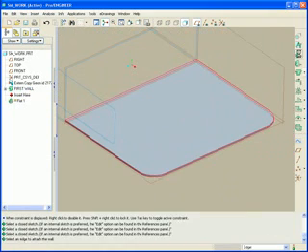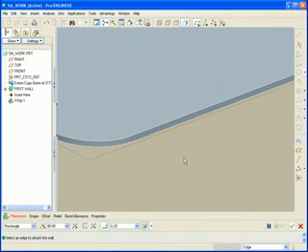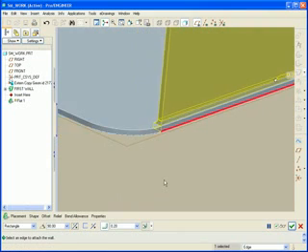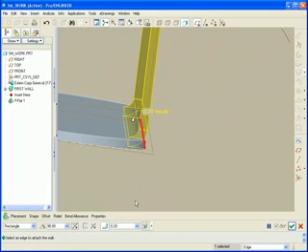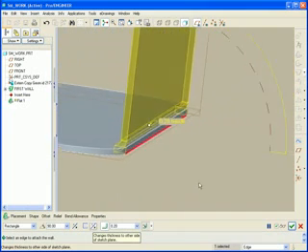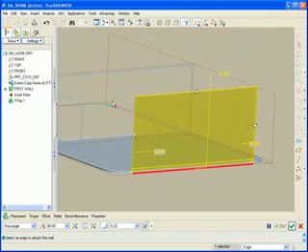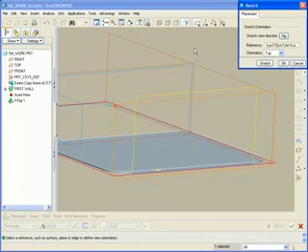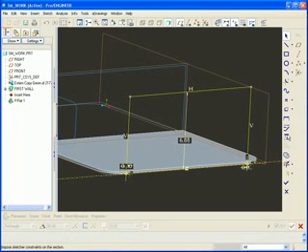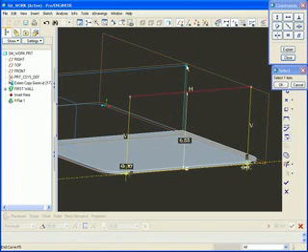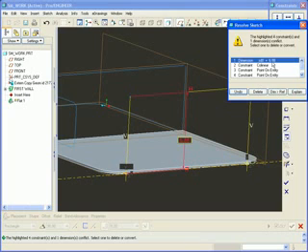Let's grab now the Create Wall, and then we'll grab an edge. Now I like to use the outside edges, and to be consistent I'll continue to use that. I want it to go in that direction, and the important thing to note here is that we put the wall on the inside. Okay, so there's our wall, and of course I can change its height, but we want it to be driven by this curve. So let's go to the Shape option, Sketch, and go straight in here and ask for this top curve to be right here on that vertex. Then we don't need a dimension.